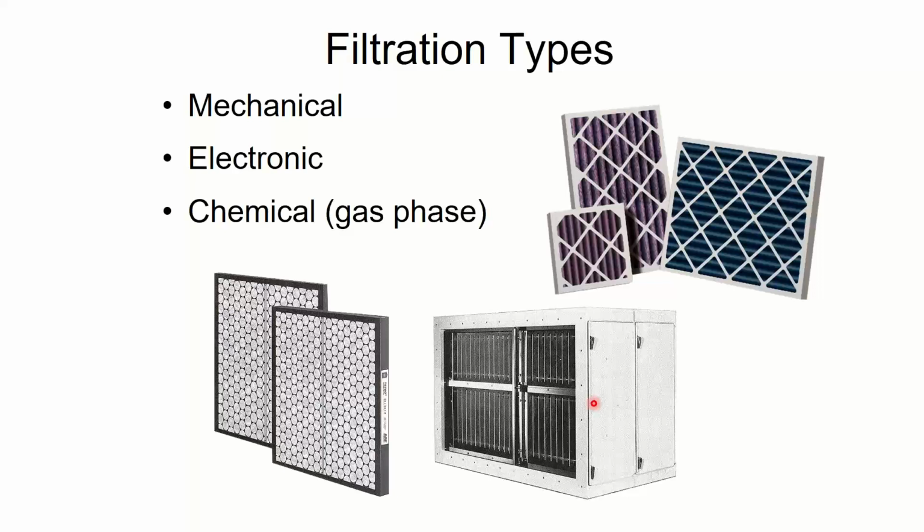The nice thing about electronic air filters is they have very low pressure drop because a bunch of plates lined up, and air can get through there pretty easily. Not a lot of restriction. So I don't need a lot of fan energy to push air through an electronic filter.